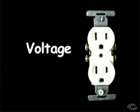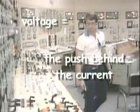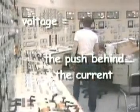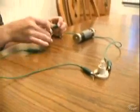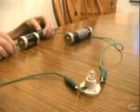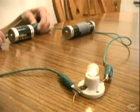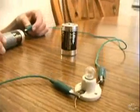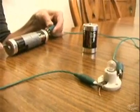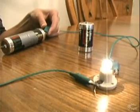The push behind the current is called voltage, and is measured in volts. You have probably seen dry cells marked as 1.5 volts. If a flashlight bulb is rated as a 3-volt bulb, it would only dimly light if we connect the dry cell to it. But if we attach two 1.5 dry cell batteries together like this, we will increase the overall voltage to 3 volts, and the bulb lights brightly.